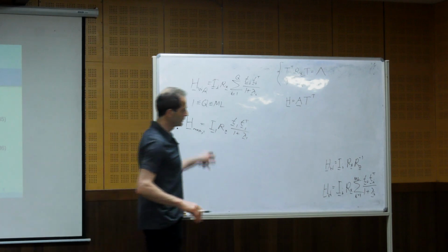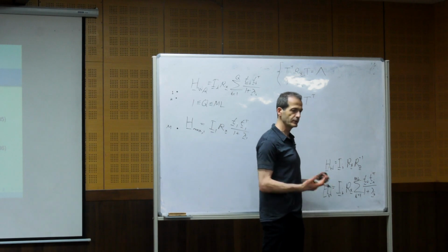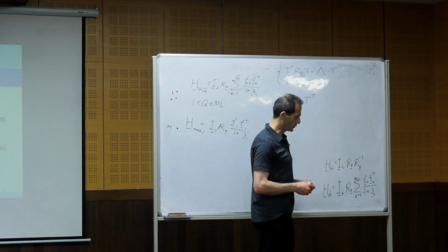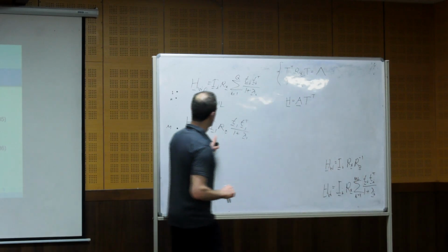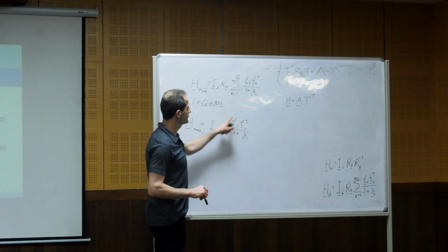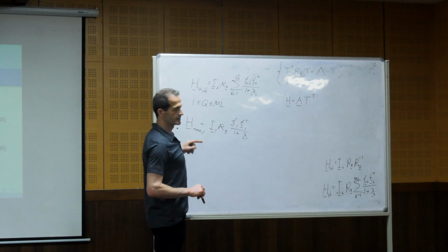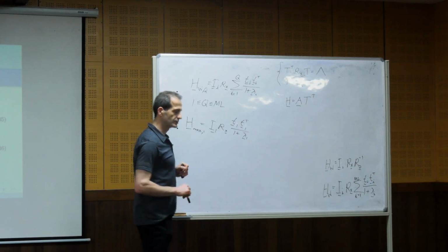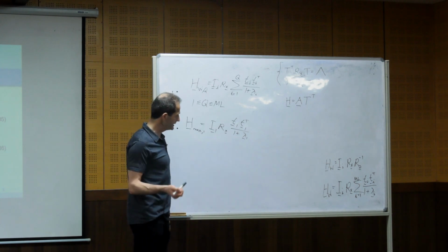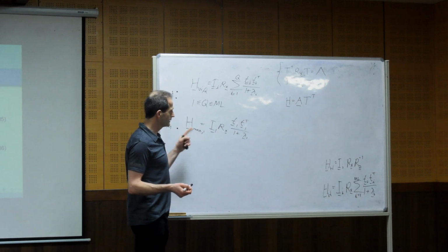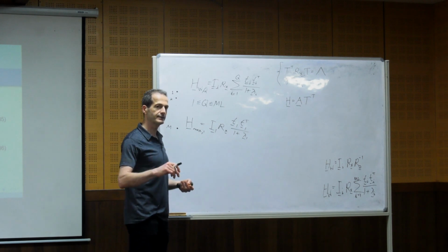You see? So from this formulation, we also obtained variable span, so we can control the trade-off between signal distortion and noise reduction. And we can also get, easily, by taking only the first term, a filtering matrix that maximizes the signal to noise ratio. And we can prove mathematically that this filtering matrix maximizes the SNR together with minimizing the mean squared error.